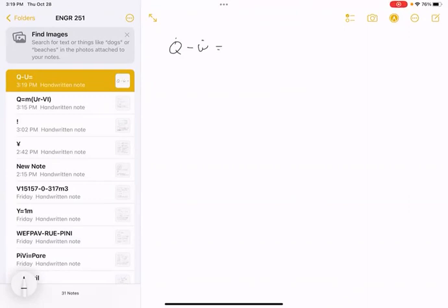Now, is the system changing kinetic energy? No, it's just a rigid tank. It's not like things are flowing in and out at some speed. Is it changing potential energy? Is the center of mass of the system moving up or down? No, they don't tell us that, so we're assuming this tank is just standing still. So we have no change in kinetic energy and no change in potential energy.